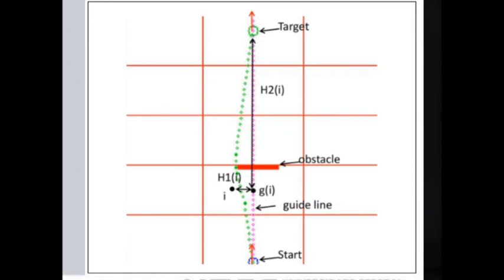So if we should penalize a point to the lateral, we just increase or decrease alpha, and in this way we choose a safer or closer maneuver here in the green points, because we select the green points based on the value of the heuristic. A higher value will be discarded. So the A-star algorithm with this modification works like this, from the A-star algorithm that I displayed in the beginning, the global planner section.